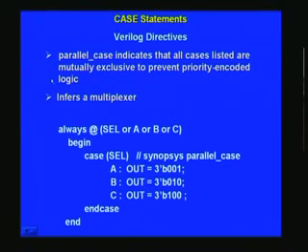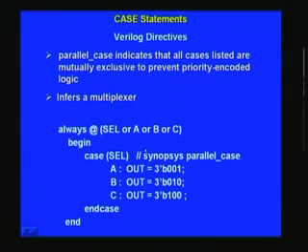And notice that it is not a must that you adopt full case and parallel case. If you are not happy with them, you can refrain from using them and use the conventional method which has already been covered in the first, second or third lectures. Another point about these directives is that they may not work in some of these systems. I'm not sure, you'll have to experiment with it and find out. But it is most likely that it will work in the Synopsys platform, which is basically a tool for ASIC design. So as far as possible, try to avoid full case and parallel case. You can write code, although it may be a little longer, but it will be safer code if you go the usual way.